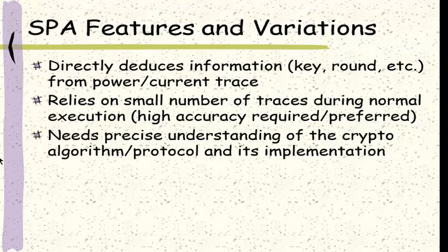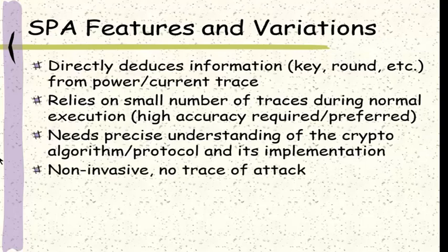To deduce secret data about the crypto algorithm from the very limited visual evidence in the power and current traces, a good understanding of the crypto algorithm and its hardware-software implementation will be critical to the success of a simple power analysis. Simple power analysis attacks are non-invasive, because the attackers will only collect the power and current traces during the system's normal execution. They do not leave much evidence of the attack either.